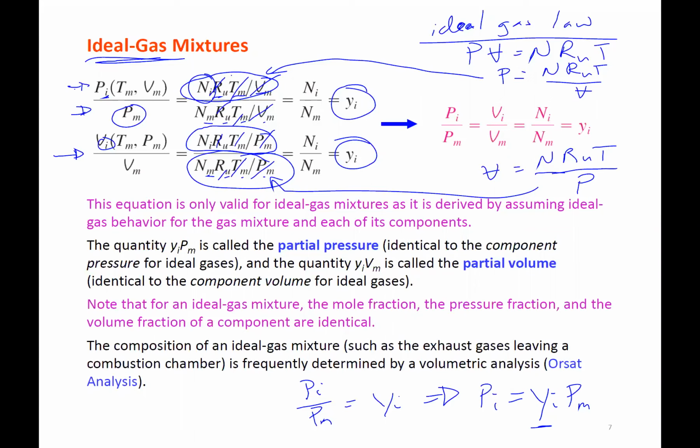And we know the pressure of the mixture, it's being released into the atmosphere, 100 kPa. Then we would know the partial pressure of that water vapor that's being released into the atmosphere. And that actually, when you get to the next chapters, would tell us about the dew point, and we'll talk about what that is later on. But that information is useful, okay, the partial pressure.